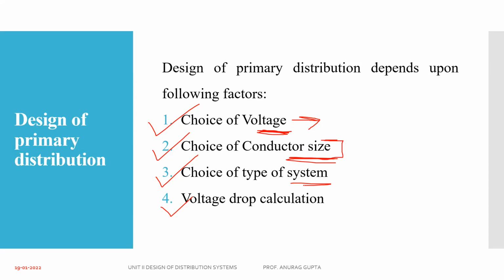Now you have to understand which one among these 3 must be used in different distribution systems. Clear? Maybe you are designing a distribution system for urban areas, like within Rajkot city, or for a rural area, such as a village near Rajkot city. So it depends on which type of system you use: radial system, parallel feeder system, or interconnected system. Which system you use for which type of area depends on the load condition.